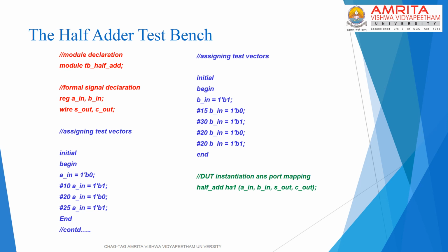But it is also possible to have different names for the ports and the actual signals which are assigned to these ports during the port mapping. So this completes the test benching process. Now the device under test can be simulated by using an HDL simulator, by running the test bench in the simulator.